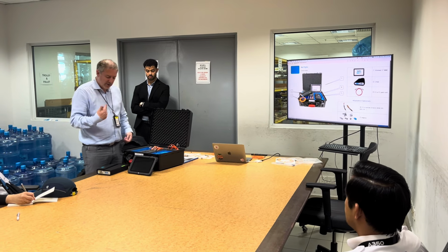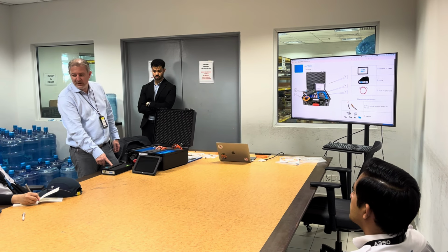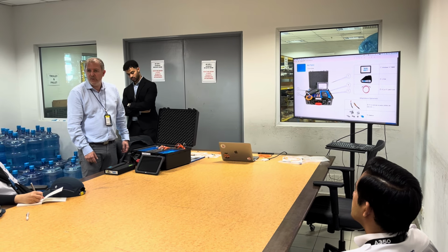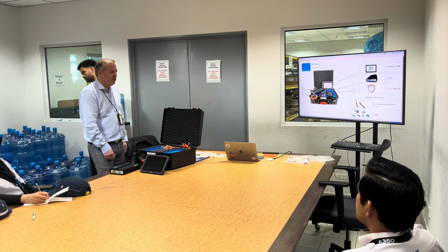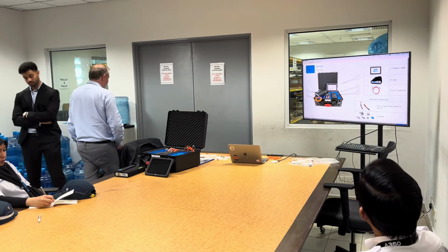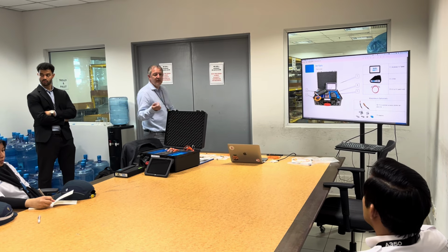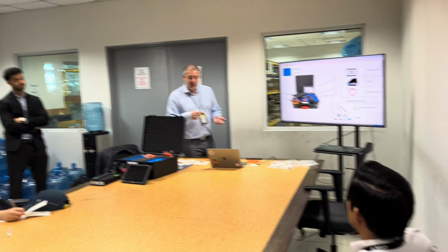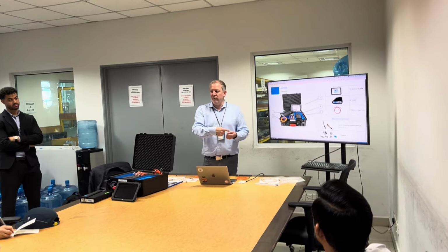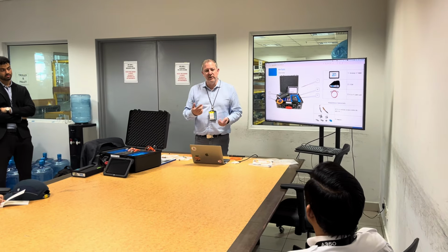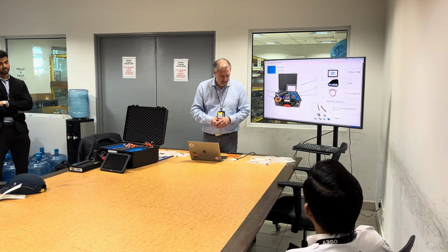So think about this as a laser system inside. Always be careful while manipulating. Also be careful when you have the fiber on the other side. If the equipment is unplugged, the light will go through and will get out of the fiber. And again, you don't see it, so be careful about that.